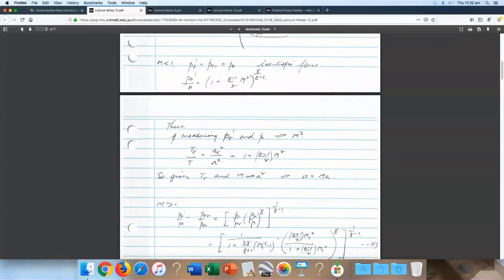Excuse me, another question. If I want to calculate the thrust while I have an oblique shock at the exit of the nozzle, and I want to simplify the problem, so I want to use the Mach at the exit where I have isentropic relationship before the shock. How far is this assumption true? Because I calculate thrust based on this Mach exit, but I ignored the oblique shock effect. How far is this assumption true?